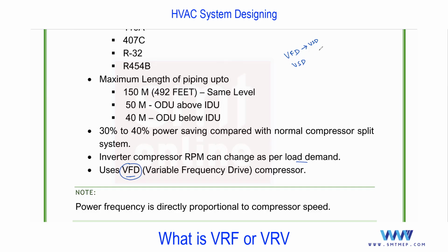It means if it is a pump, compressor or a fan, remember this technology is for all: compressor, pump or fan. Pump means I'm talking about the chilled water pump or condenser pump, we'll discuss. And fan you'll find in the AHU and in the FCU. In that also you'll find this technology, especially in the AHU, for power saving. So remember, if you find this VFD technology, by default it's a VSD.